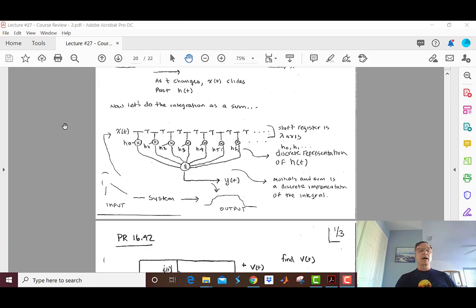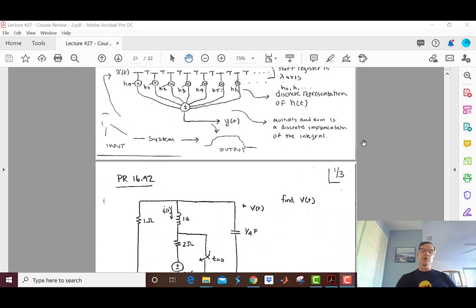I like this view of convolution best because it puts it in terms of digital filtering, and now I can see it. I can see the music going through all these memory locations. And with each tick of the clock, it gets shifted through this 8 or 12 or 20-bit shift register, then multiplied. And that's exactly what the operations in a digital signal processor do.